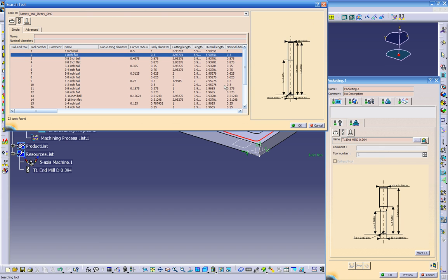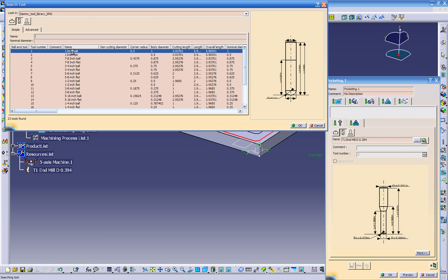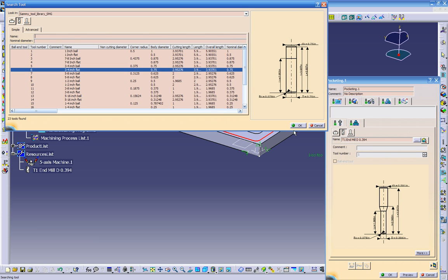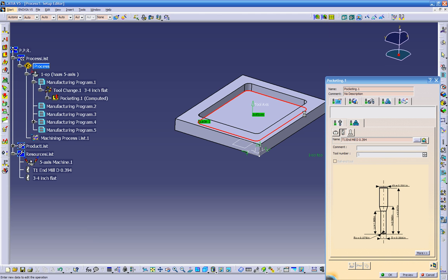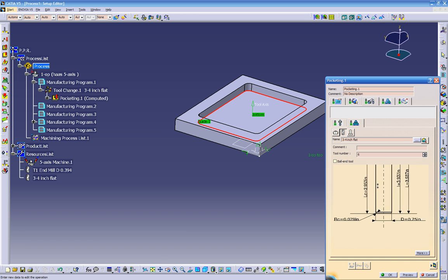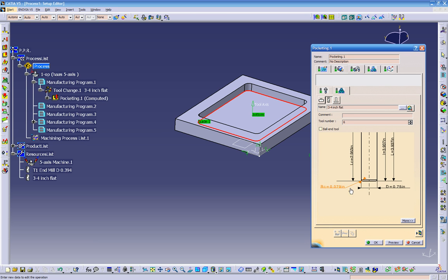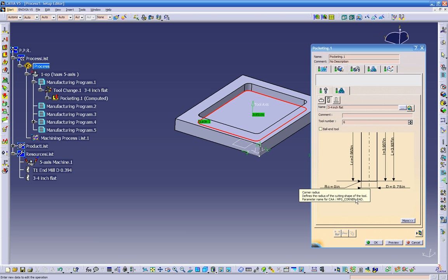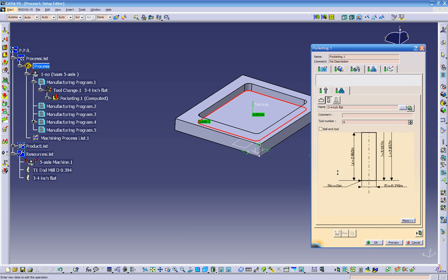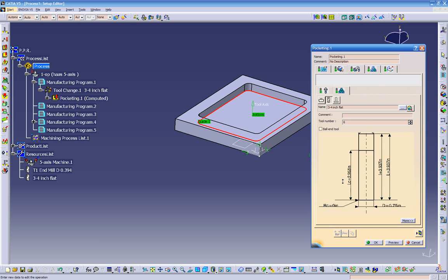For example, let's say we want to choose a 1-inch flat. Let's click on 1-inch. 3/4 flat. Click OK. And you can customize it. Even my operation, even though I said it's a 750, for some reason it puts this radius in here, but you can double click on it and make it 0, make it a sharp corner. And you get your tool over here, customize.